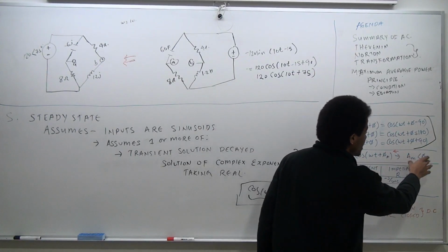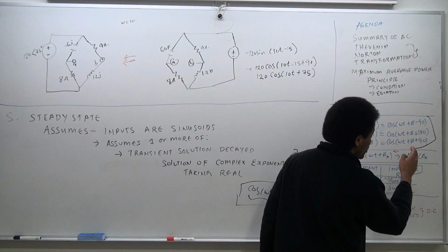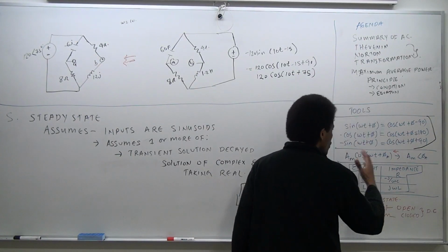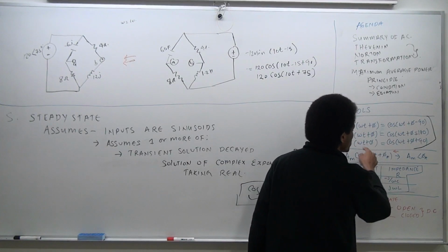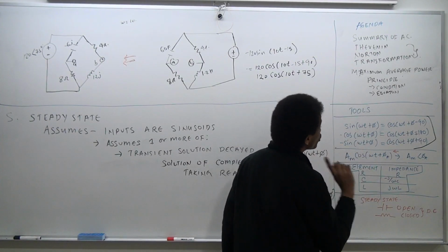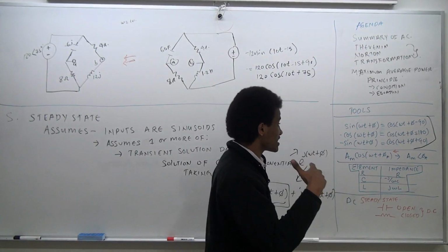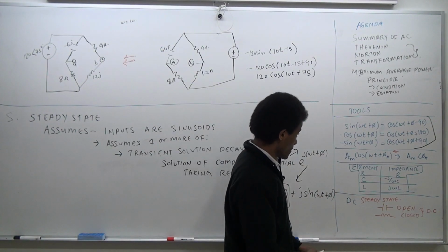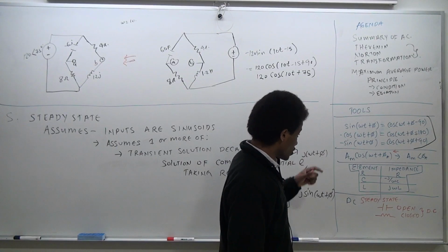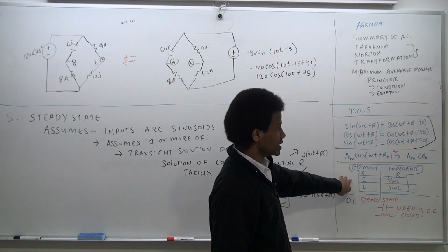Realize a phasor and a complex number are the same thing, but when you're coming back from the frequency domain to the time domain, you're going to have to include the temporal information that you kept aside. But you don't do that with impedance. Impedance is just a number. It's not a function. It's usually considered fixed for passive elements.